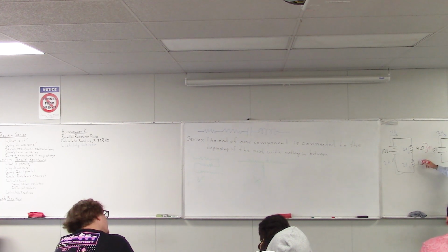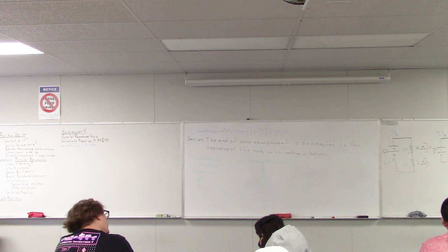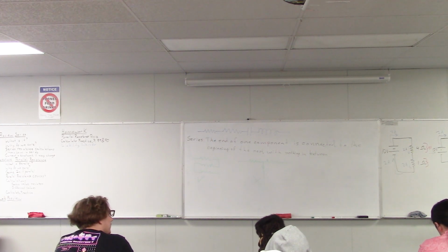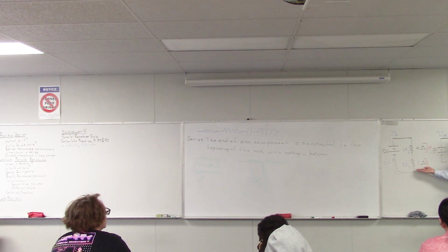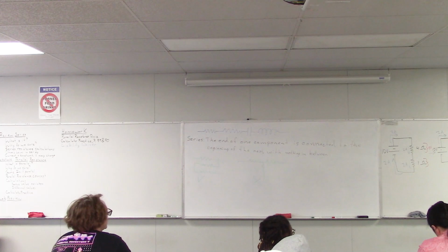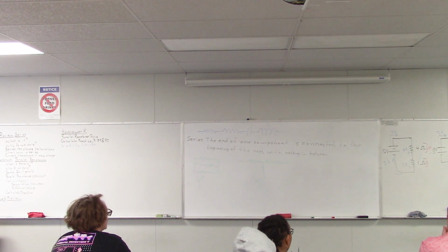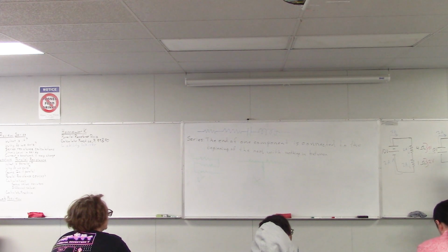We can also figure out the voltage across this resistor down here. So again, we say V equals I times R. What is the current for this resistor? 2 amps. And what is the resistance there? Yeah, 1 ohm for that resistor. So that would be 2 amps times 1 ohm, and that comes out to be 2 volts. So we have a 2-volt difference from one side of that resistor to the other. So, are there questions about that?